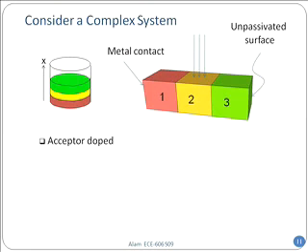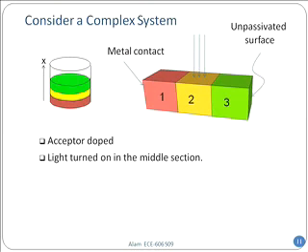So the first thing it says, I'm solving a problem, let's say it's an exam problem, that it is acceptor doped. So you immediately realize in your head that this is essentially all acceptors, and p, the number of holes in the extrinsic region, is equal to Na, right? That's the first thing you immediately realize as soon as you hear the words acceptor doped.